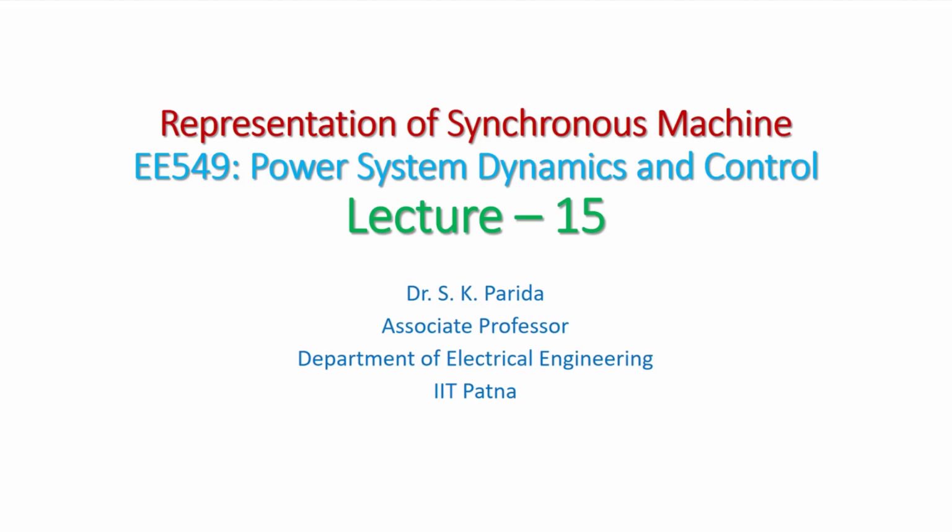But now we have to choose a reference frame which is common to all the machines and also common to the transmission network. Now how will we represent the synchronous machine under that condition? We'll study it and do the analysis as well.